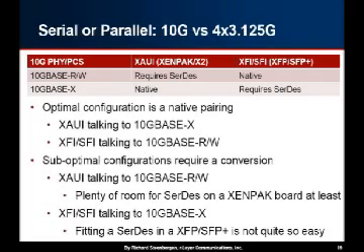So obviously the ultimate goal is to match technologies. If you have an optic that transmits 4 parallel lanes and you have an interface bus that uses 4 parallel lanes, connect the dots, it's real easy to implement. When you have to go between the two, that's when it starts becoming problematic. So optimal configuration is XAUI talking to something that's 10GBASE-X, or XFI talking to something that's 10GBASE-R or W. And the suboptimal configuration is obviously the mismatched version of that.